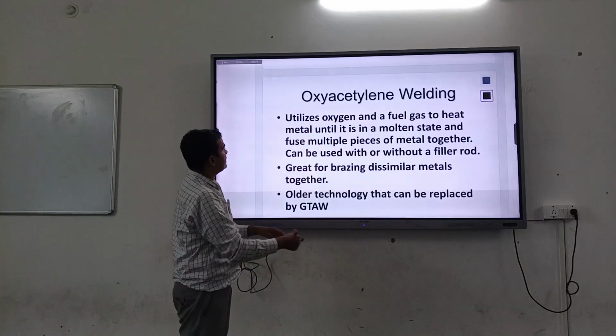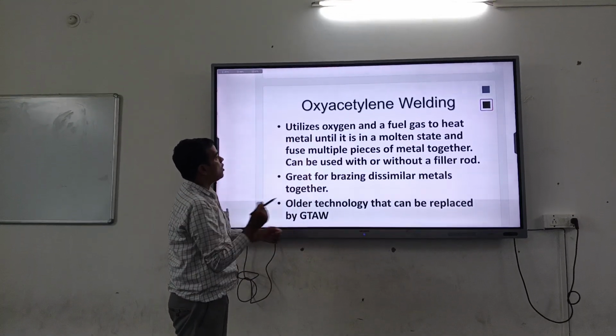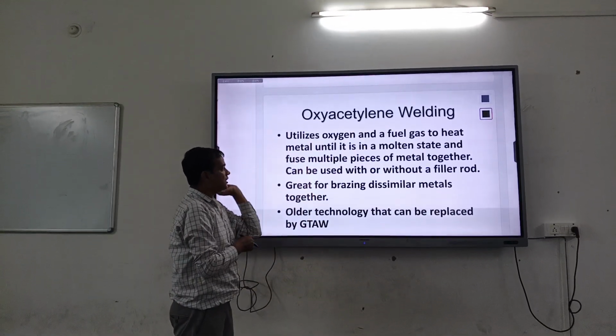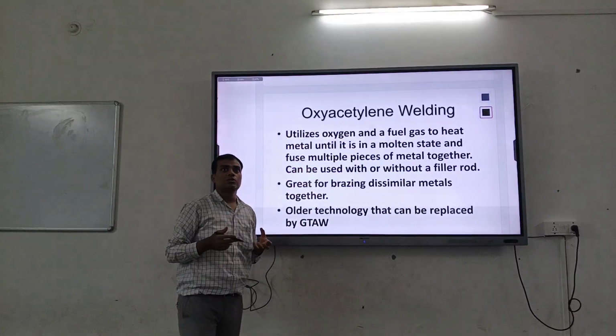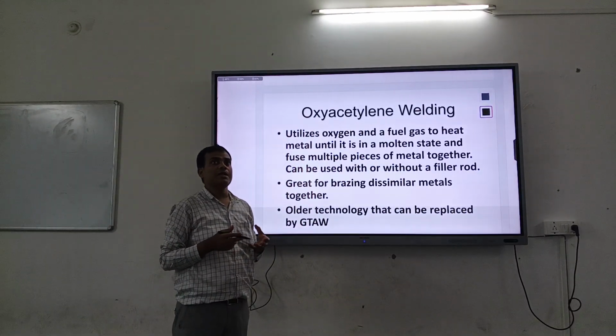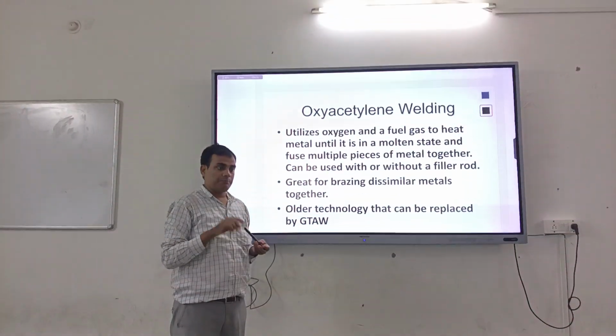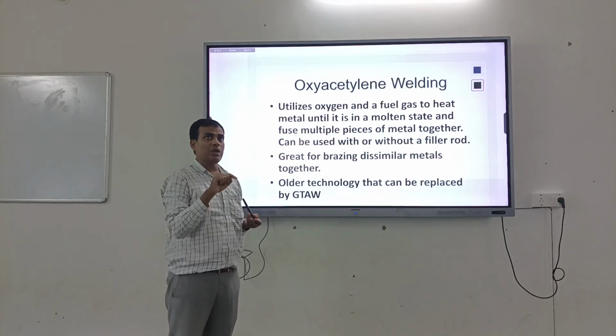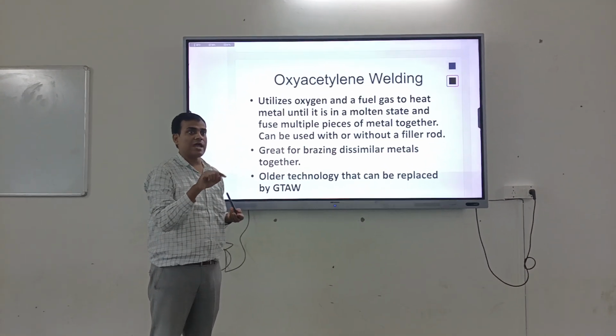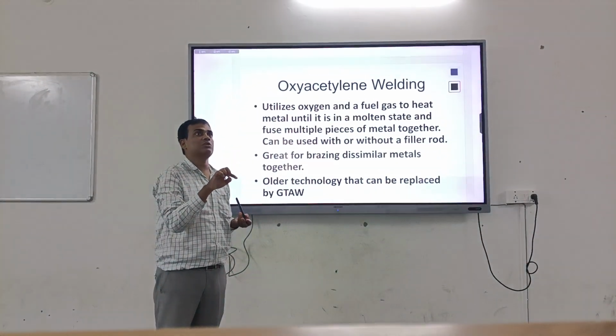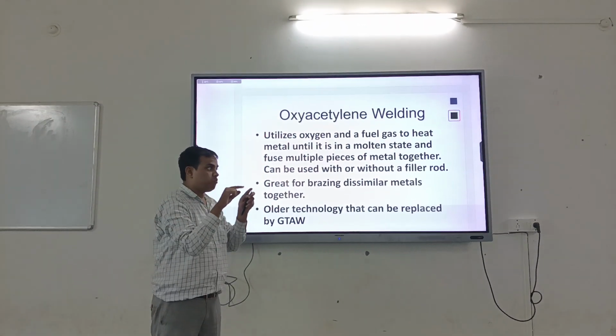welding. In this welding, acetylene and oxygen gas are used, and they mix together in the equipment, and then combustion starts, and the pinpoint flame transfers the heat to the joint position. It is only for a point joint.